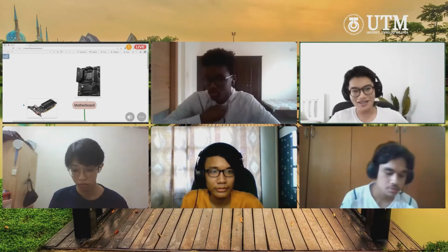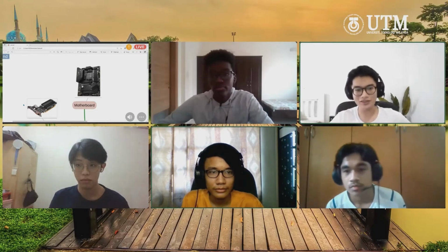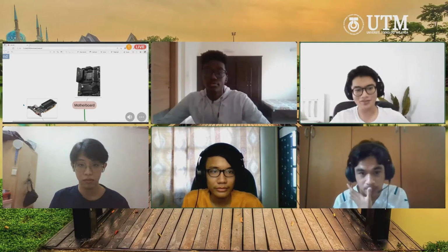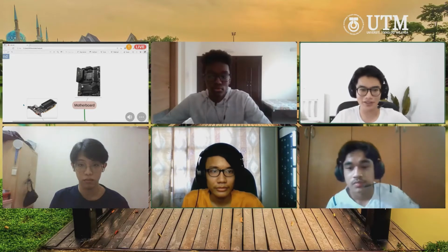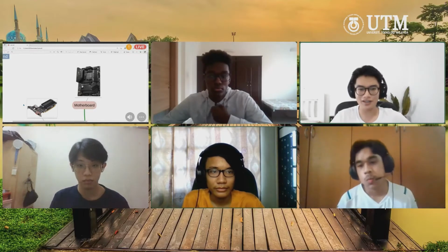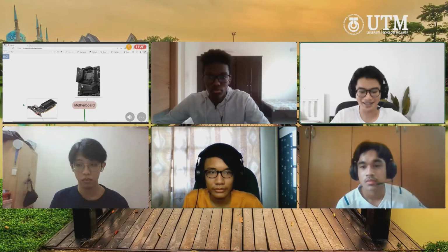Hello, I'm Azhan. I will be telling you about the ways to install motherboards and the tips. So for installing the motherboard, first of all, you obviously need to open your computer case, and you also need to ground yourself to a metal or any metal item.